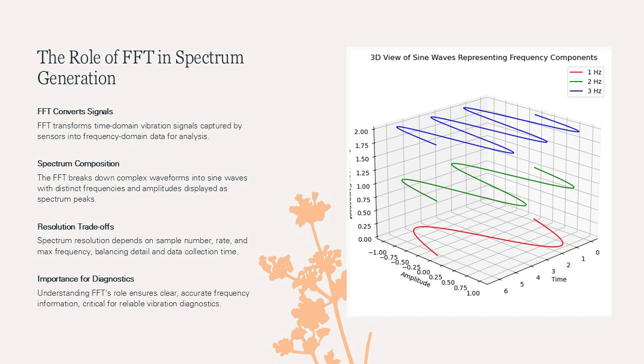The resolution of the spectrum depends on factors such as the number of samples, sampling rate, and maximum frequency, Fmax, selected during data acquisition. Higher resolution provides more detailed frequency separation but requires longer sampling times. Analysts must balance resolution with practicality to ensure accurate diagnostics without excessive data collection time.